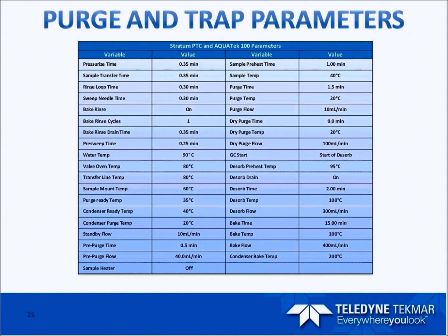So after some method development, limit curves, all that stuff, this is where we're at now. This is what we found works really well with our new trap. It's driven by rapid analysis. We want to do things as fast as we can, so that's why we're pushing the envelope on trying to get cycle times down. Keep the samples cold, and the less you have to handle the sample after you start to sample it, the better. So we've gone with a 5 ml sample volume to keep everything as cold as possible and do the least amount of sample manipulation that we can, because we found that more sample manipulation gives you worse reproducibility. So that definitely is something that we went with moving forward.